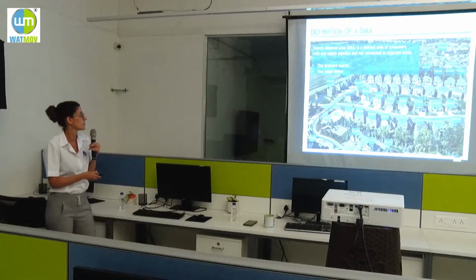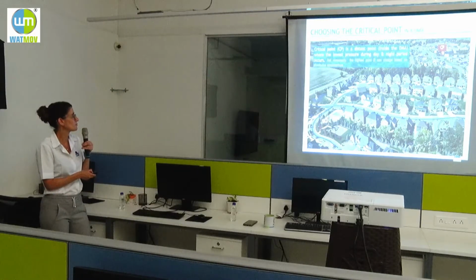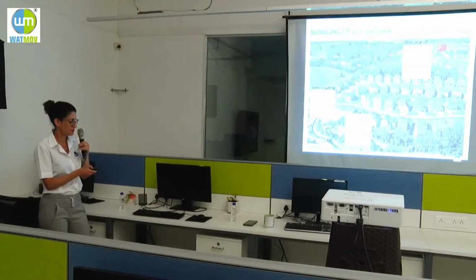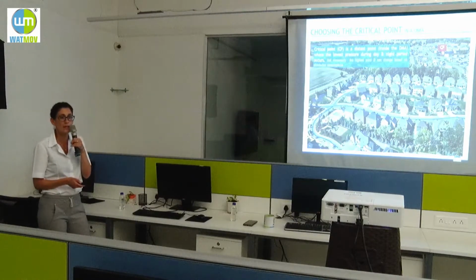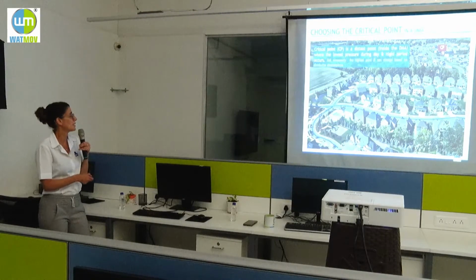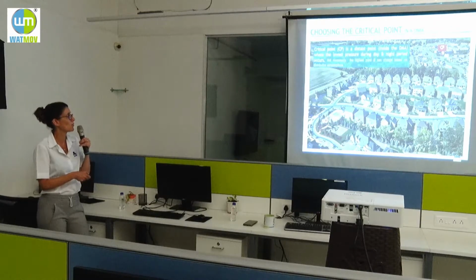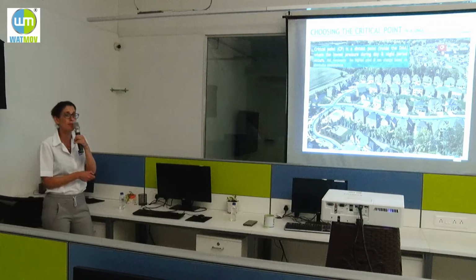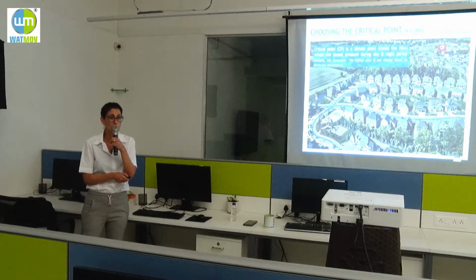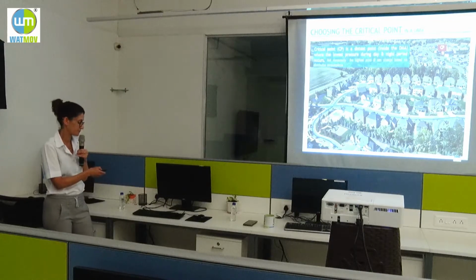Okay, let's continue. This is the critical point, right? You can see here the critical point. We now need to supply water to this entire DMA and make sure this critical point gets sufficient pressure 24/7, at peak hours as well, at rush hours, when demand is high.